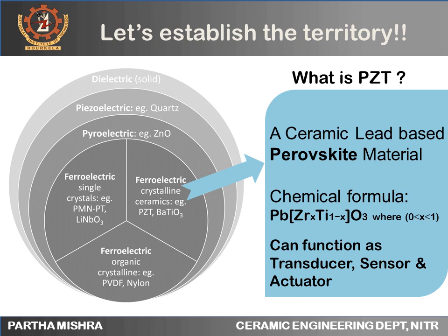So to increase the capacitance, we require a dielectric material, as introducing it in between those plates would increase the permittivity beyond that of air by a factor of epsilon r, which we call the relative permittivity or the dielectric constant of the material. Over recent years, we have encountered materials whose dielectric constants are much larger, in the range of tens of thousands. This means we can now see a much higher polarizability in these advanced materials. For example, in PZT, the dielectric constant can be around 450, hence it can polarize to a much higher extent.